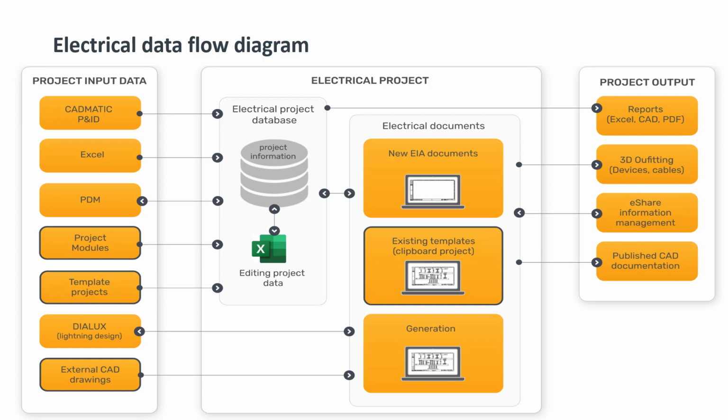Is it in DWG format, in DXF format? We can also import IFC models as a reference model for our electrical project and electrical model. Regarding the electrical project, it is database based. As I have mentioned, there are two technologies, Microsoft SQL or Access. We can make changes in Excel, and the database is connected with the documents. And regarding the documents, we can create new documents from scratch. We can reuse the existing templates using, for example, the Clipboard project, or we can generate documents.